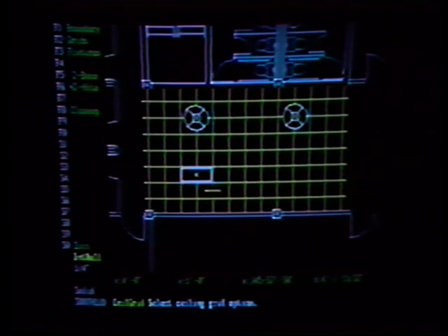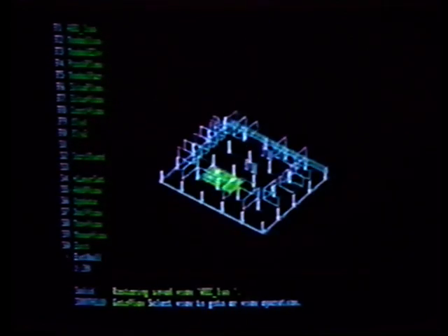And so what you've seen me do here in a very short amount of time is to create an entire office building using these automated routines in DataCAD AEC. And what we haven't yet seen is that many of these routines are three-dimensional, which means that if I were to go over to a parallel view of this, I could see the building in isometric.